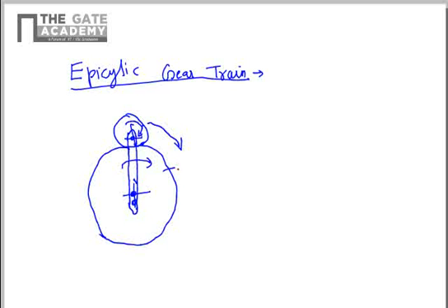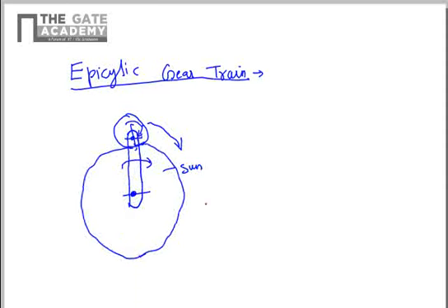So the terminology used here is that the bigger wheel is called a sun since this is usually a fixed gear. Although the modification of that is also possible, that we will cover in the subsequent topics. For the time being, we consider it a fixed gear, the sun, and the smaller gear will rotate about its own axis. It will have a rotational motion, as well as it will revolve around the sun gear. This motion is similar to planets in the solar system, which rotate about their own axis and revolve around the sun. So this gear is called a planet gear.